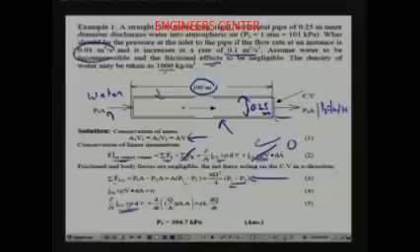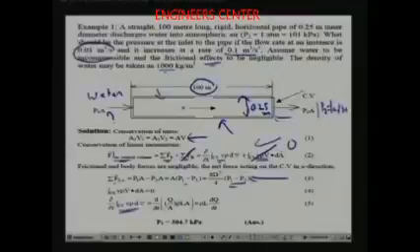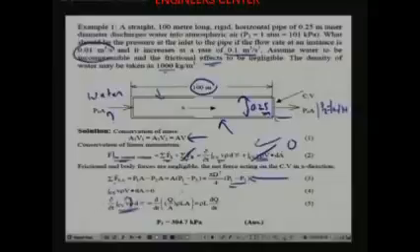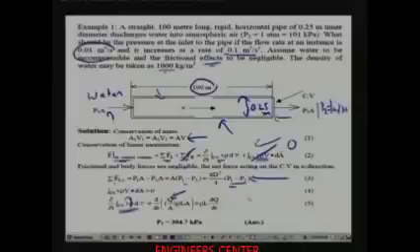So this is the net force acting on the control volume in the x direction. So this should be equal to the rate at which the momentum of the control volume is changing. The rate at which momentum of the control volume is changing is this, and here the small v is the momentum per unit area, which is some kind of velocity, and this can be written as volumetric flow rate divided by the cross sectional area. That means v is equal to Q by A.